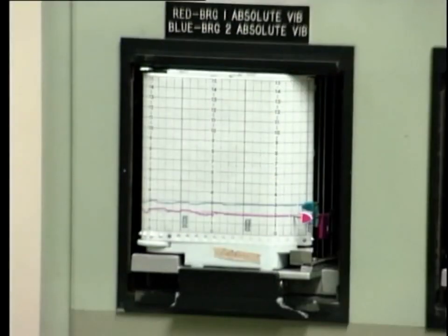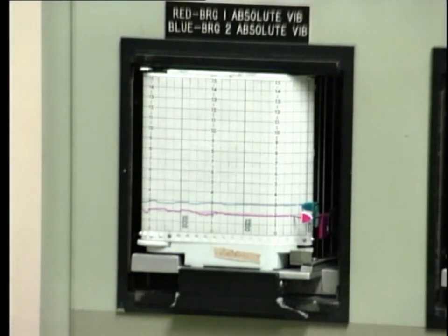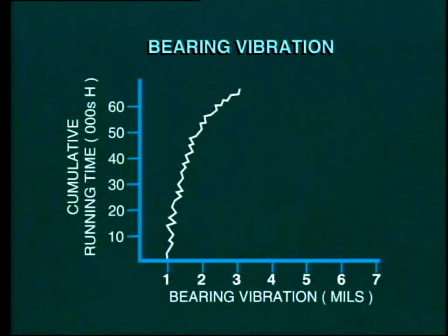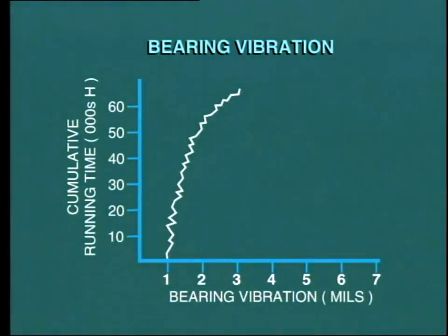Similarly, a temporary increase in turbine bearing vibration may be an indication that the operator is applying load too fast. If the magnitude of vibration on all turbine bearings steadily increases with time, it is probably an indication of wear and tear on mechanical components as the machine approaches the next overhaul period, usually every 5 years.